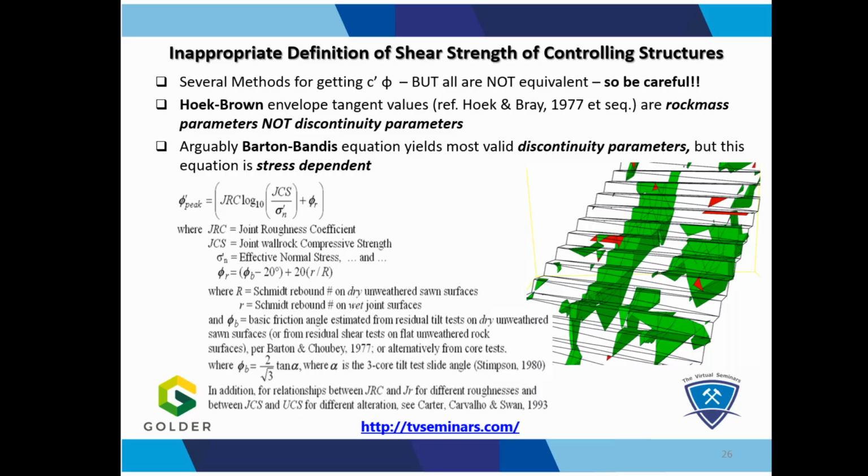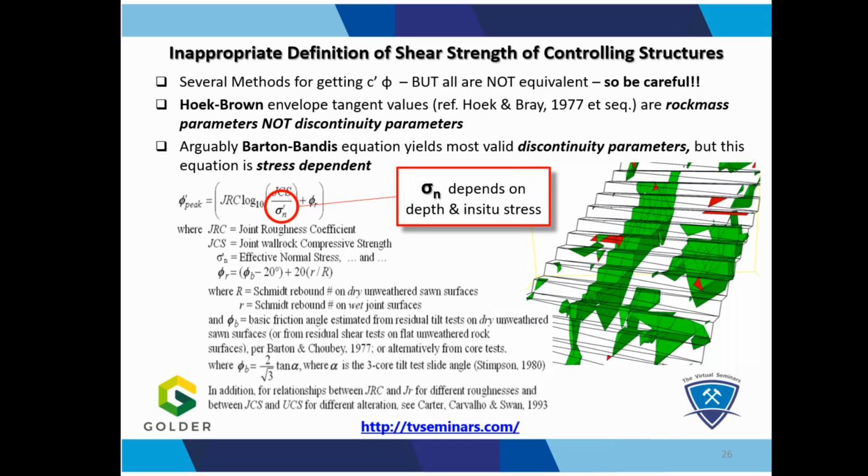But we have to be careful. These are all stress dependent. And so if we are looking at single value numbers for C and phi, maybe we shouldn't be. These are things that need checking. They're the things that make our models unreliable.